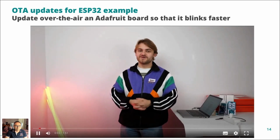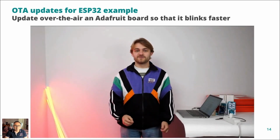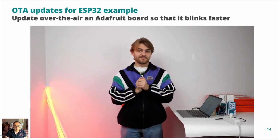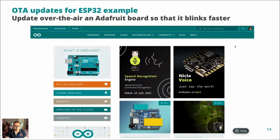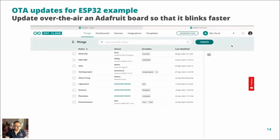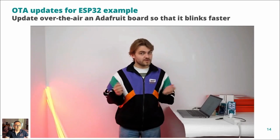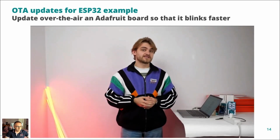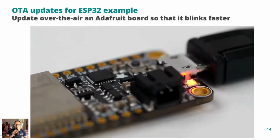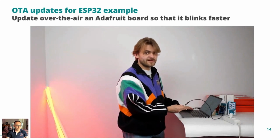Today, I'm going to show you how to perform an over-the-air upload to an ESP32 development board using the Arduino IoT Cloud. To access the Arduino IoT Cloud, go to arduino.cc and log in or register if you haven't already done that. Then you can go to this menu in the top right and click on IoT Cloud. So I already have my device configured in the cloud. And now I'm going to upload a blink sketch just to test it out. Okay, so now the board is just blinking, an example we're all very familiar with.